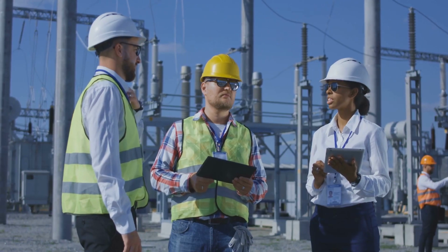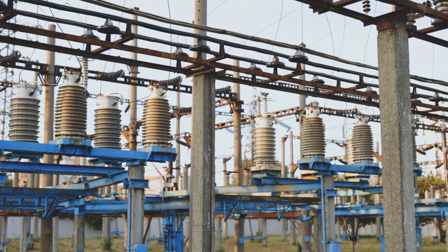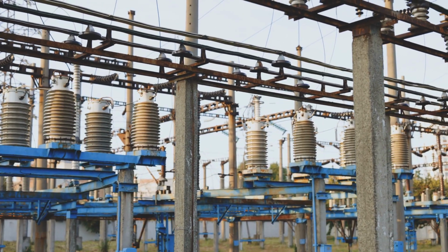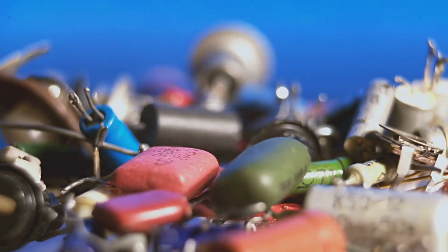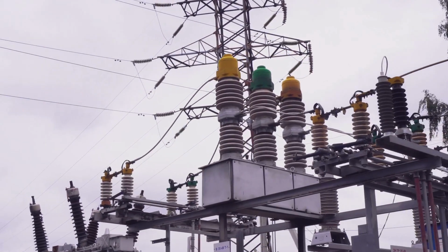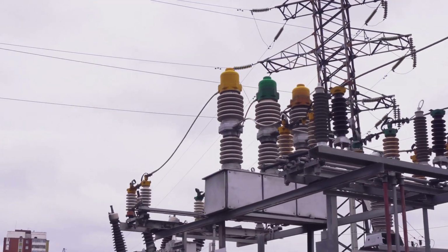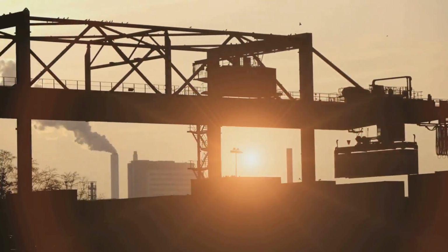So, what is power factor correction, or PFC? Power factor correction is a set of methods designed to improve your power factor by reducing reactive power demand. One of the most common tools for this is the capacitor. Capacitors supply reactive power to your system, so your electricity company doesn't need to provide as much. This reduces apparent power drawn and, in turn, lowers your costs.